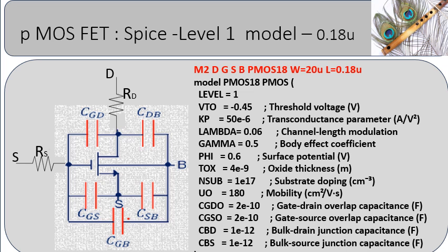The level of a MOSFET model in SPICE indicates the complexity and type of the mathematical model used to describe the behavior, taking into consideration phenomena like short channel, velocity saturation, leakage currents, etc. The level indicates the model accuracy, simulation speed, and relevance to actual silicon behavior. Lower levels like 1 to 3 are simple models meant for education or older technologies. Applicable technology node, like micron or nano level, indicates the technology or feature size.